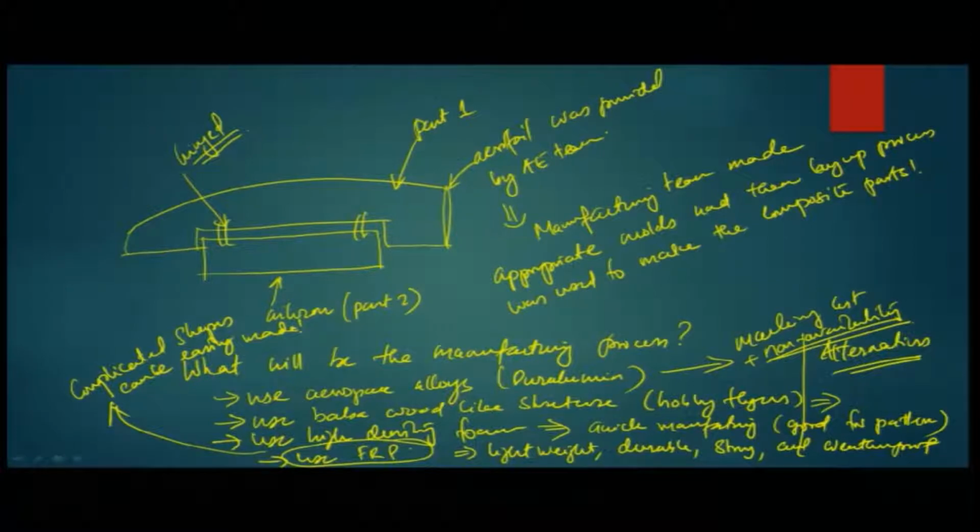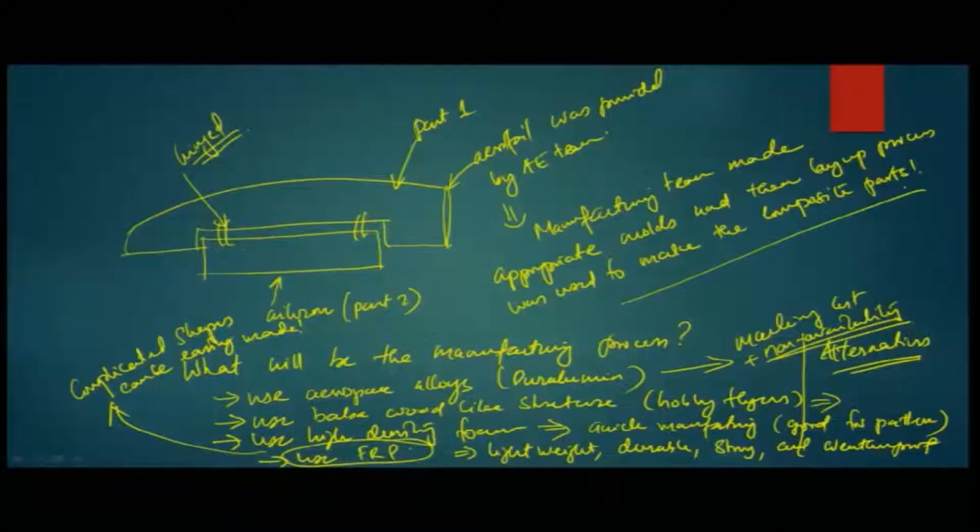Because of all these things, it was finally decided as the trade off in this process that we will use composites. Once this was decided, the next major thing was what will be the mold or what are the patterns. Then making the patterns, from there the imprint of the part is taken out. So, that process was started.